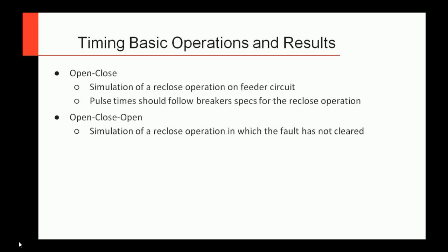But if you really want to be thorough, you want to go ahead and do your reclose operation, where maybe the real-world conditions, a lightning strikes the line, the breaker trips, clears the fault, closes back in, fault's gone, no problem. One thing to pay attention to here is you want to make sure your pulse times are long enough and that your reclose timer is set long enough so you don't do damage to the breaker.